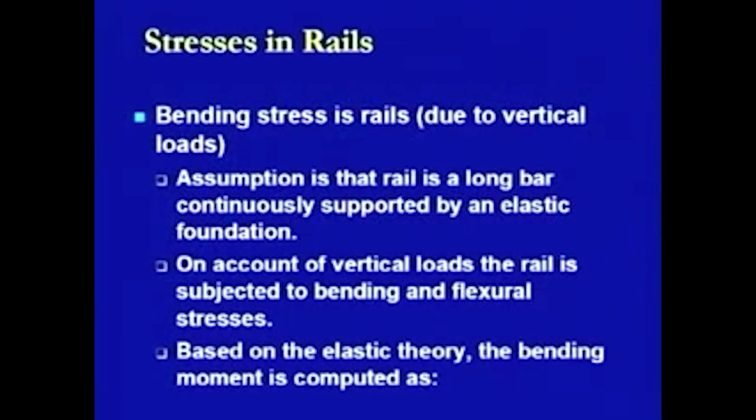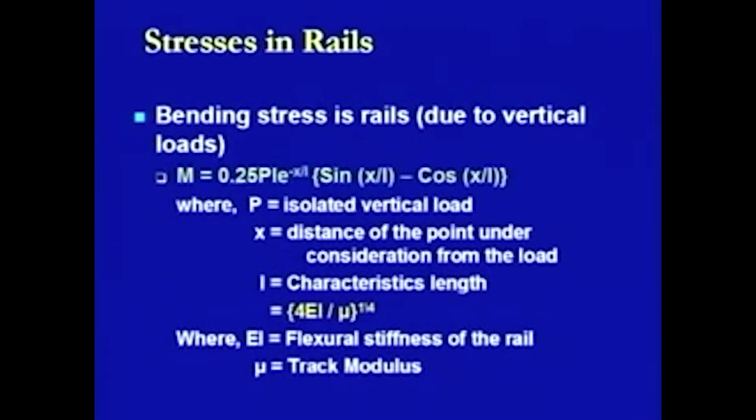loads. Now, based on this elastic theory, we can compute the value of the bending moment, and this value of the bending moment can be computed in the form of M equals 0.25 P into L into e raised to the power minus x divided by L, and this is multiplied with sine of x divided by L minus cos of x divided by L. This is all taken into one parenthesis and is multiplied with the rest of the values.